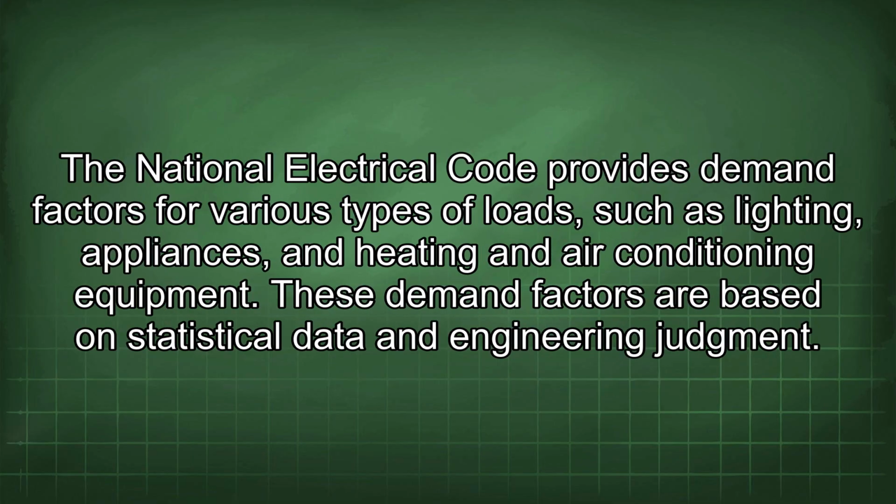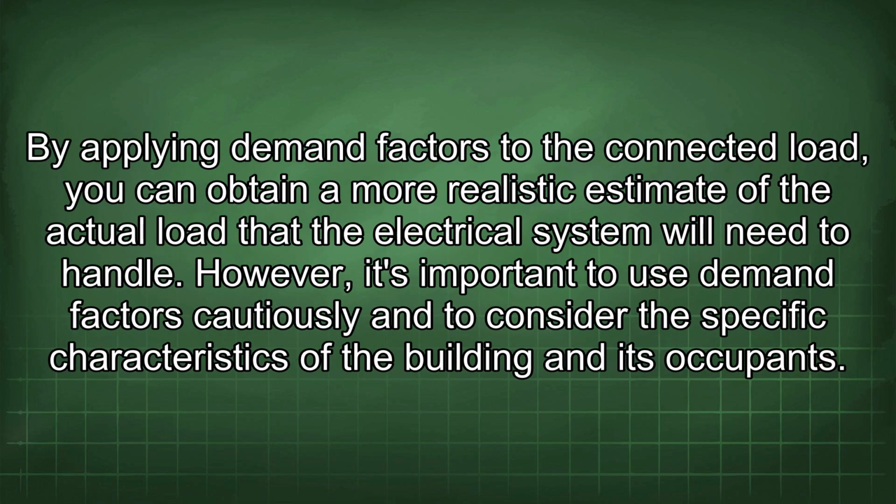The National Electrical Code provides demand factors for various types of loads, such as lighting, appliances, and heating and air conditioning equipment. These demand factors are based on statistical data and engineering judgment. By applying demand factors to the connected load, you can obtain a more realistic estimate of the actual load that the electrical system will need to handle.